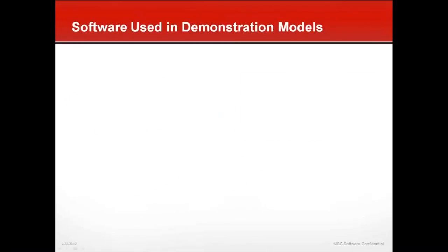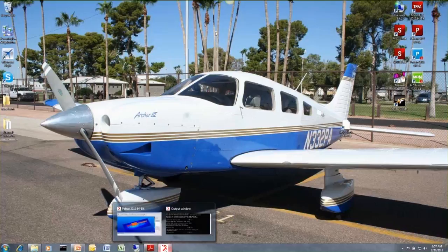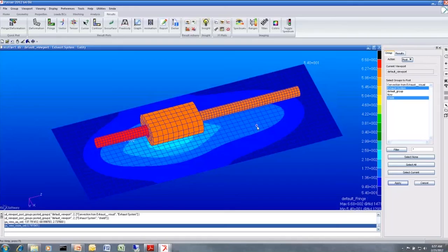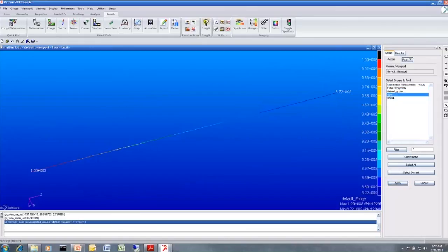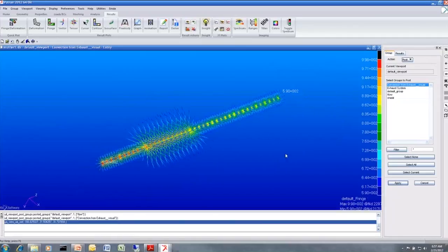So let me take just a few minutes here and pull open Patran. And here's this exhaust problem here. And inside this, I have some airflow, which is just a bar conductor, and that bar conductor was hooked to all the surfaces that formed the exhaust pipe, and these conductors were automatically computed that hooked up the airflow to the surrounding walls.